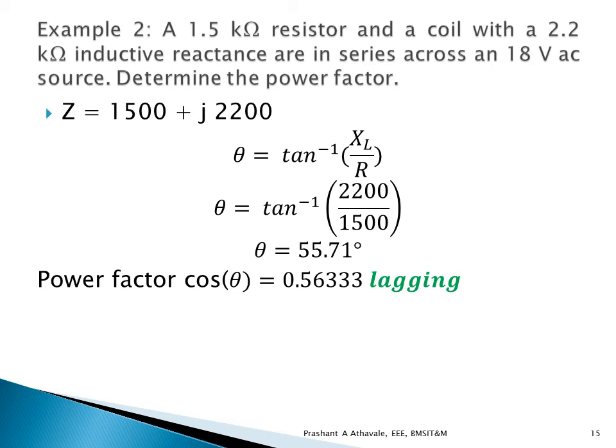You can recall from our previous slide that theta is equal to tan inverse of XL by R. So theta is tan inverse of 2200 by 1500, and you can determine theta as 55.71 degrees.